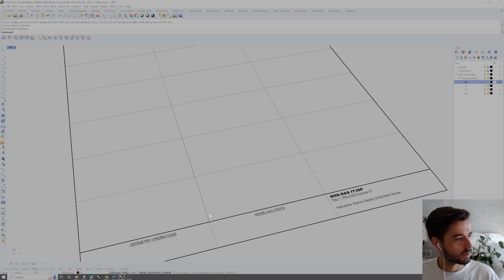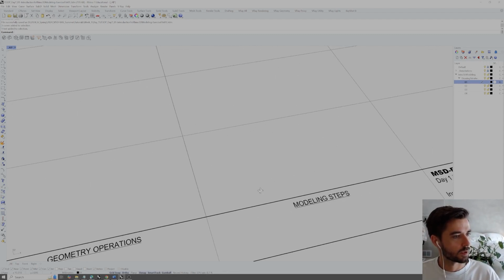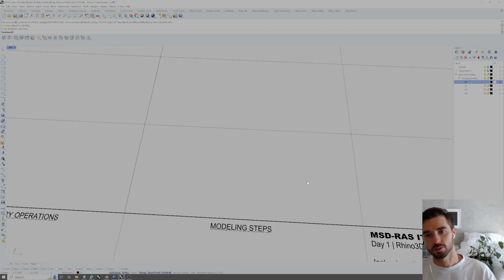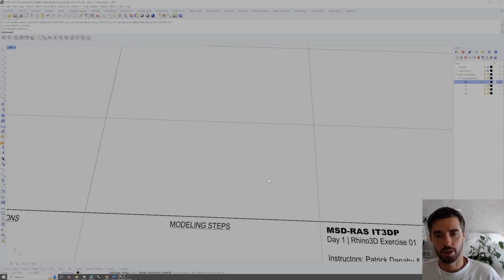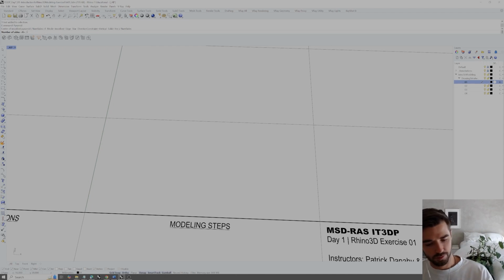And then I'm going to zoom in here towards the origin, which is this middle rectangle cell space. So we know that in a tetrahedron, each of the edges are going to be equidistant. It has 4 faces, and it is a kind of triangular pyramid. So if we know those things, we could just type in pyramid. We could change the number of sides to 3, and then this is going to give us a center-inscribed pyramid, so inside of a circle of a given radius.